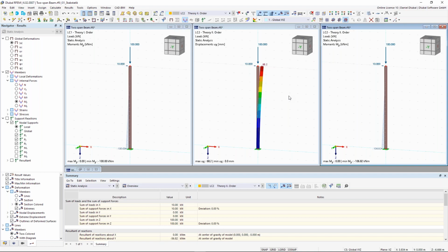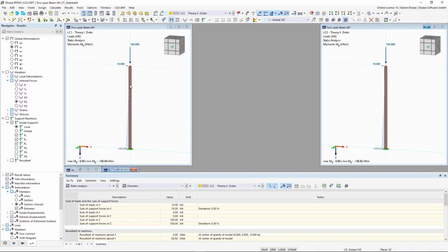Now stability analysis. You see here we have the Euler case 1. We have 4 different Euler cases. This is something you have to know. And for the Euler cases, you can also calculate and consider the buckling length and also the critical loads. And in RFEM, we can also calculate and determine these things.